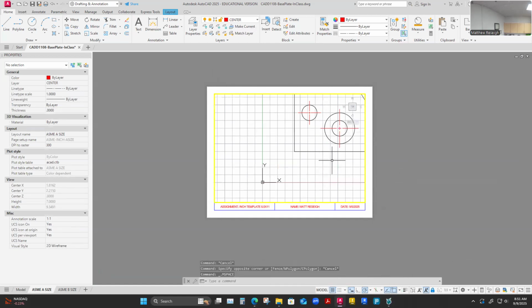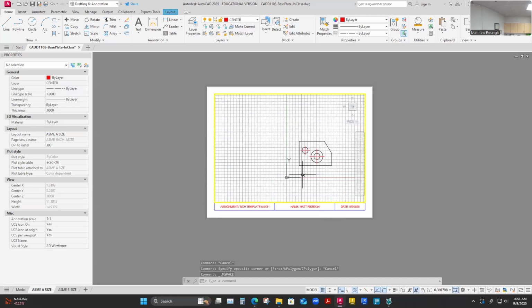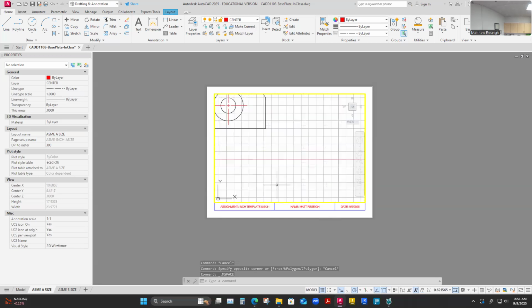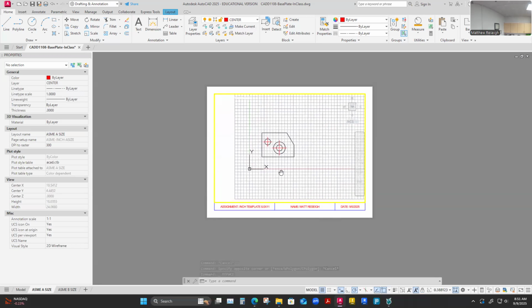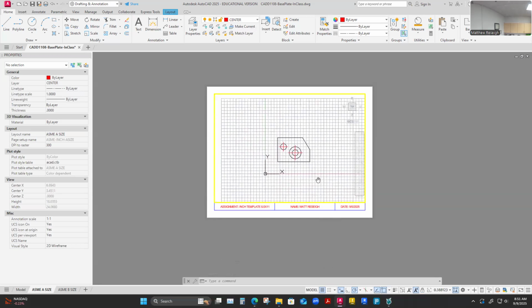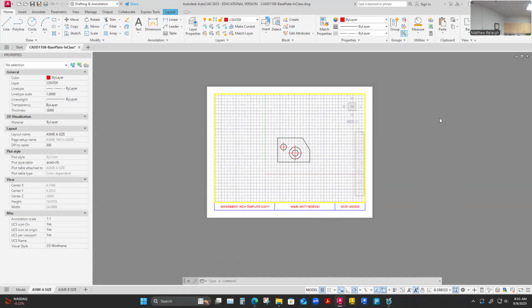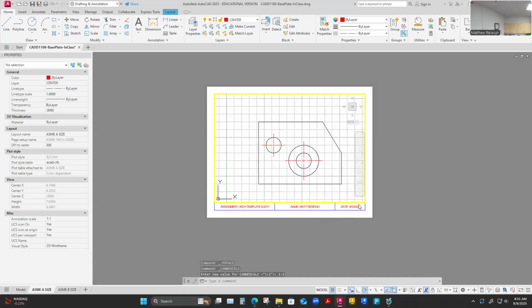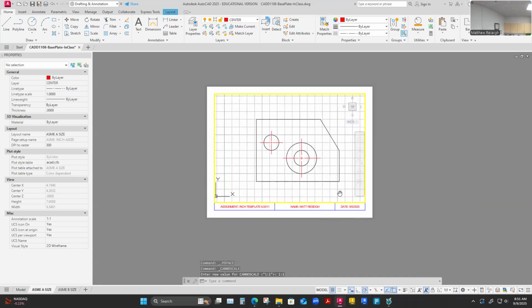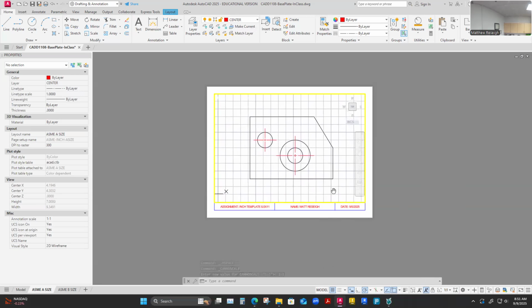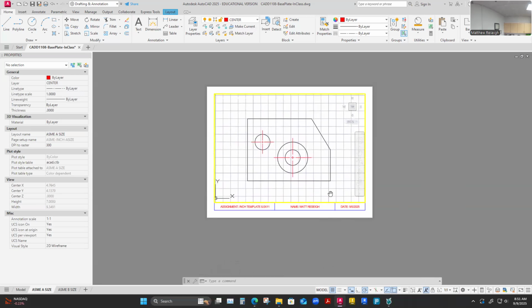So I got my navigation wheel. It shows me I'm in there. Now I should be able to unlock it, and then scroll to fit this, pan it over, and find out where I can fit. I just click my mouse wheel to hold and pan. The drawing instructions say to draw these at 1:1, essentially. So I'm drawing them 1:1 in model space, but they're going to fit on our paper in full scale, essentially full size. This fits easily. And then I just want to center it. I can just roughly center it. Bam, like that. That's good enough.